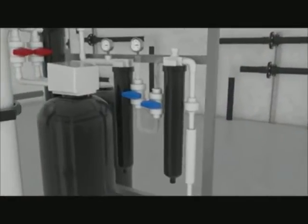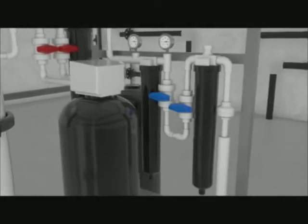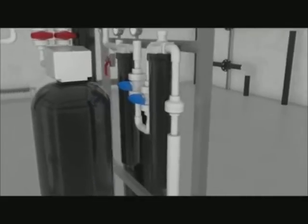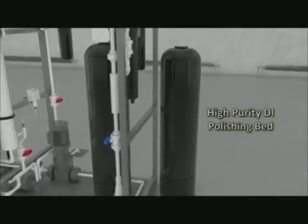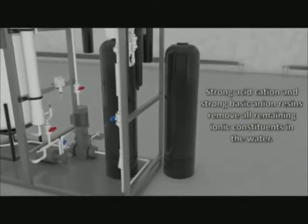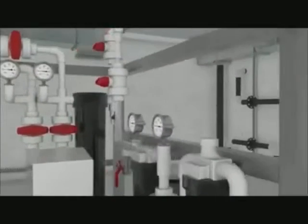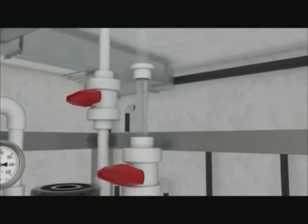The UV-treated water is passed through a final filter, usually sub-micron, to filter any organic or non-organic matter from the subsequent ultraviolet treatment. In some cases, further ionic removal will be needed to meet deionized water quality. If this is required, Process and Water implements a DI polishing bed containing strong acid cation and strong basic anion resins to remove all remaining ionic constituents in the water. The product water has been post-treated and is ready to be sent to the points of use.